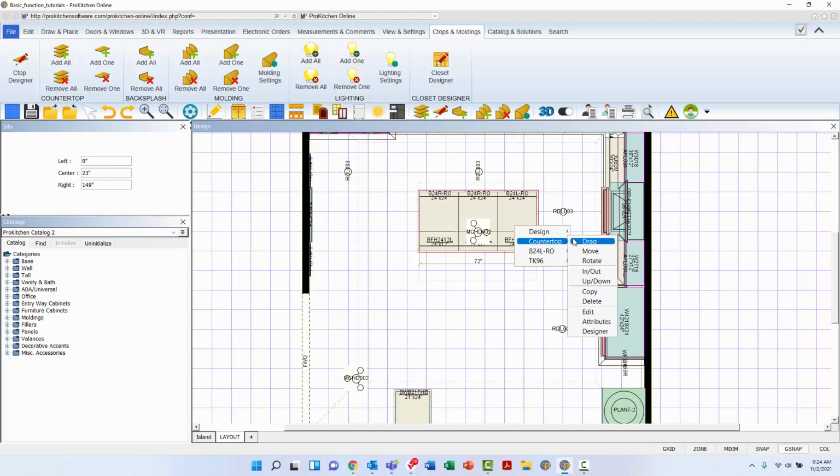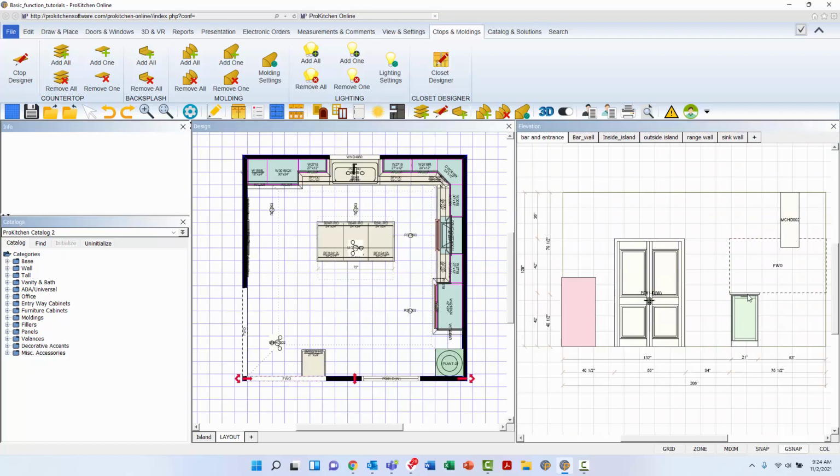The first option in the toolbox is Drag. This tool may be used in either the plan or the elevation view. When selected with a left click, Drag will allow you to drag the countertop left or right in relation to the wall zone in which it is placed. You may move it manually with the mouse and left-click to secure.